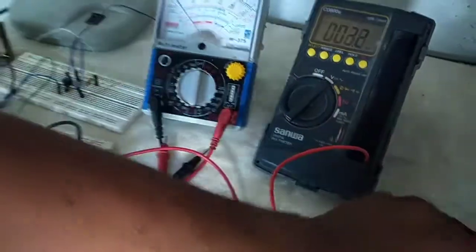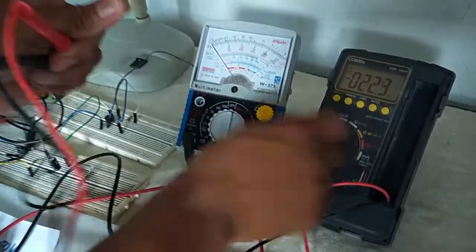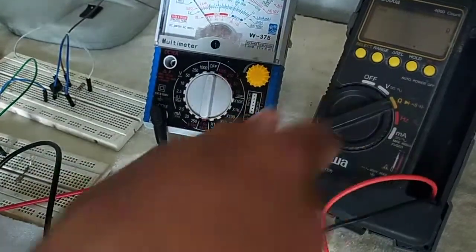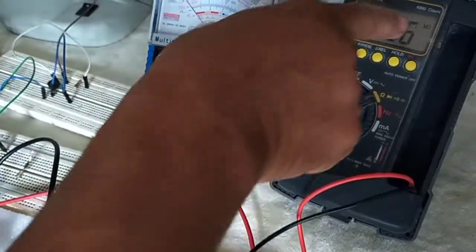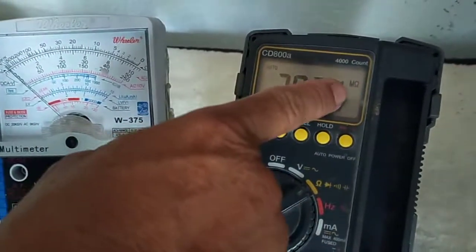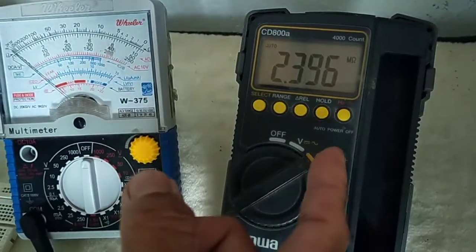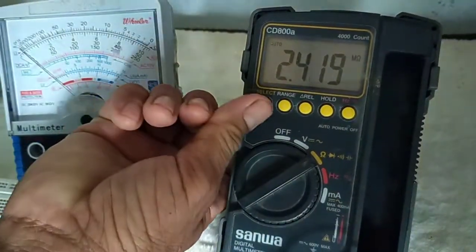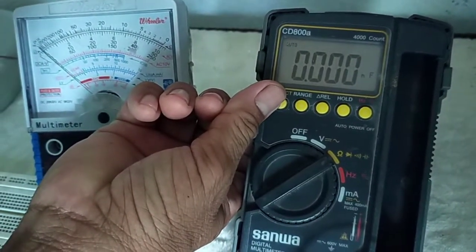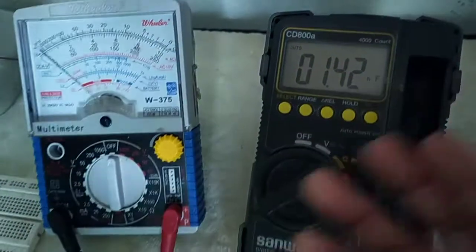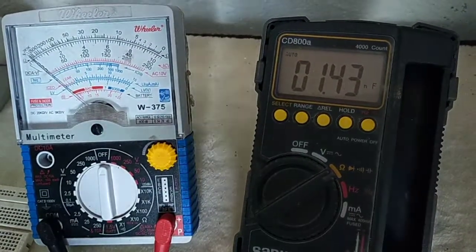9.54 volts. Or, if you wish to measure the resistance of this resistor, we have to move the range selector switch to ohmmeter. Then, we can tell we are at ohmmeter because the unit indicated at top is megaohms. Remember, with this position, we can also measure the capacitance by pressing this selector here. Okay, that is voltage, ohms, nanofarad, right? So with this position, it is designed to measure resistance and capacitance.